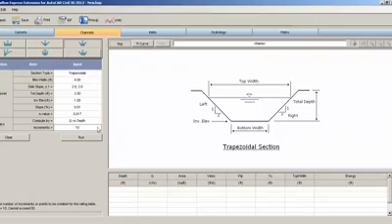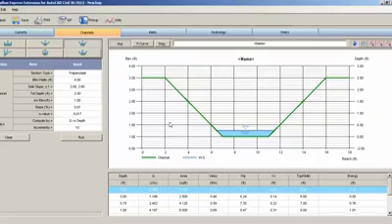And the increments here show how many steps you have in this channel from the first point to the end point, or the distance of the flow. So I will leave it as 10, then I use Run. We get this. Here is showing the elevation, and here is showing the reach, and in the other column, the Y direction, here is showing the depth.